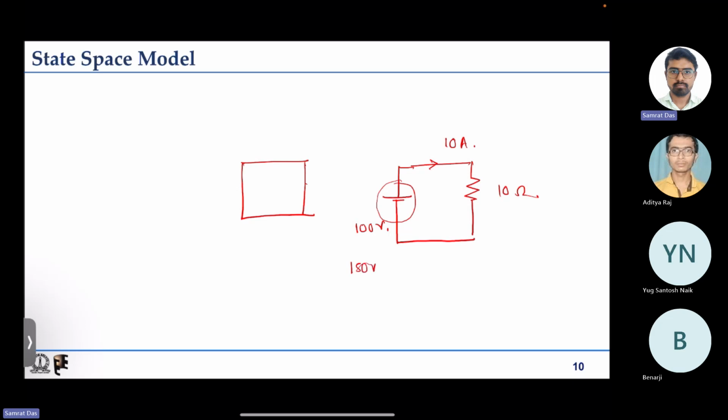If it is a variable DC voltage source, your controller will be tweaking the actual voltage. But if the maximum voltage is only 50 volt, no matter how much your controller tweaks around the control input, it will not be able to pass 10 ampere current to that.